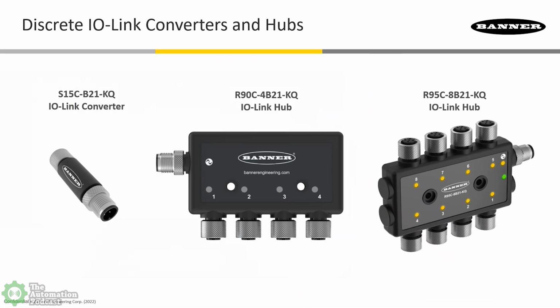A couple of case points came up to me while you were talking. Number one, if you have analog that you're having a lot of noise issues with because it has to run through an area that's very noisy, that's one place where converting it at the source to IO-Link would help alleviate the noise riding on that analog signal.